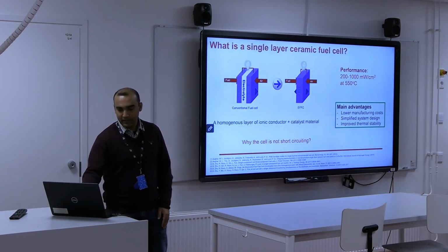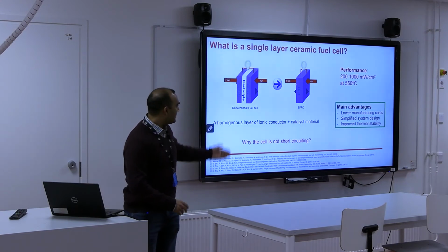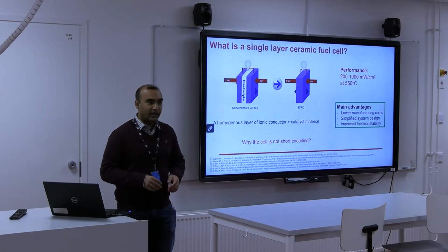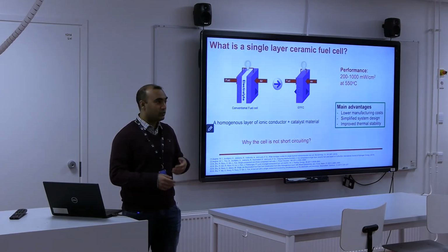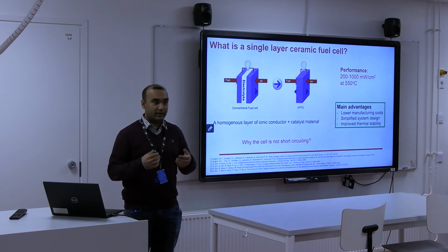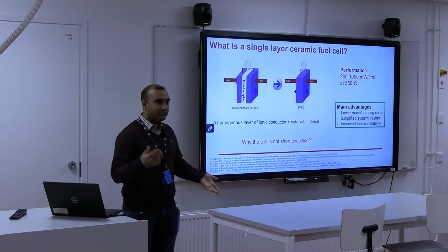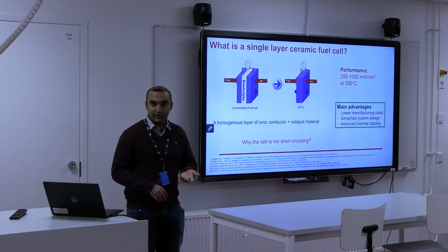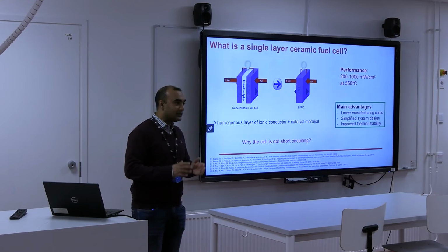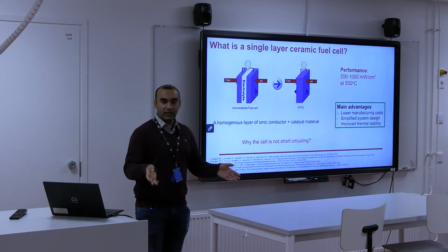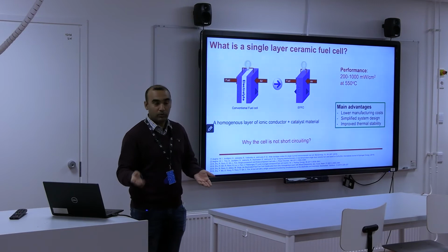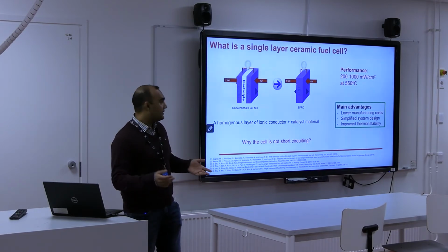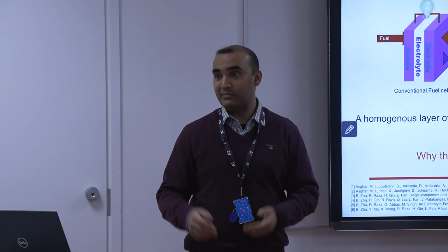The good thing about this single layer is it has lots of advantages, because as I said, when we have three layers, they have different materials, different thermal expansion coefficients. At higher temperature, we have higher thermal stresses. In a single layer, there are not so many stresses, so it has improved thermal stability. And another good thing about this single layer cell is that if you switch the gases, air on the other side and fuel on the other side, it still works. It just changes its polarity. So it's amazing.